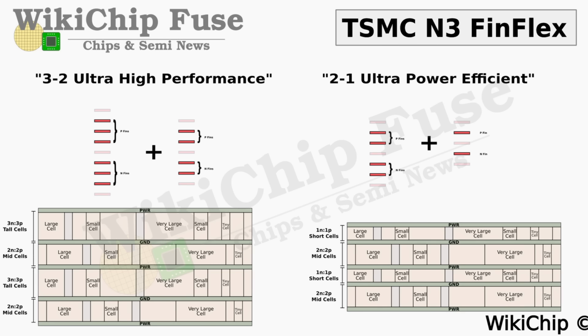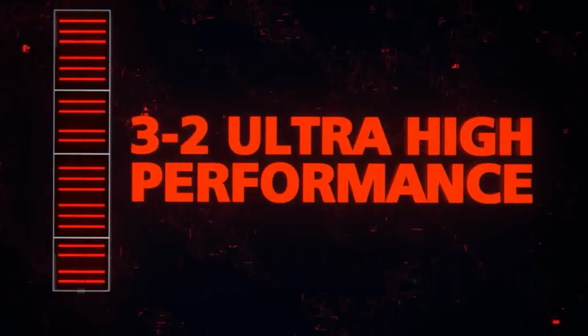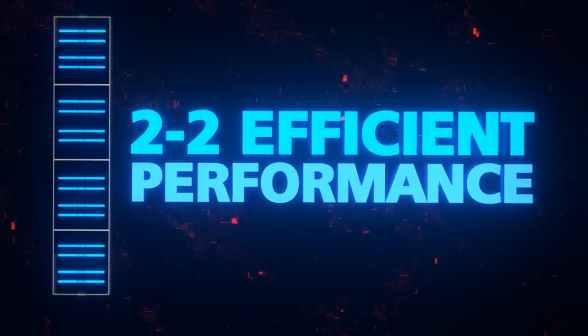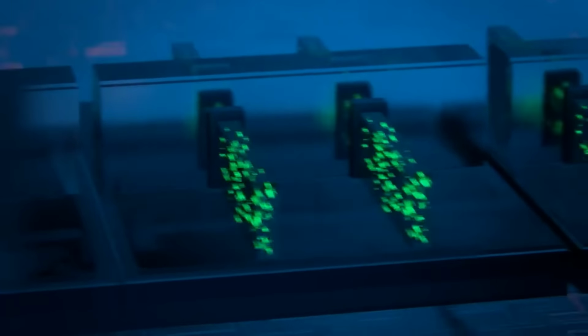As a result, chip engineers have more options to fine-tune the process to achieve the highest transistor density. Before FinFlex, you could choose if you want to use cells based on a 3-fin or a 2-fin design. That was the entire amount of customization. With FinFlex, you now have 2 more in-between steps. A combination of 3-fin and 2-fin cells inside a single block results in an average of 2.5 fins. And the combination of 2-fin and 1-fin rows has an average fin count of only 1.5.